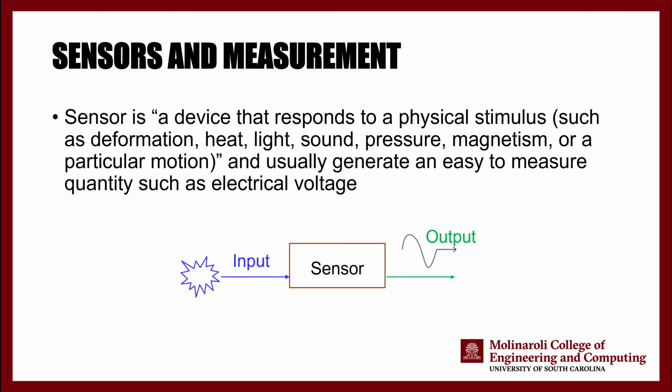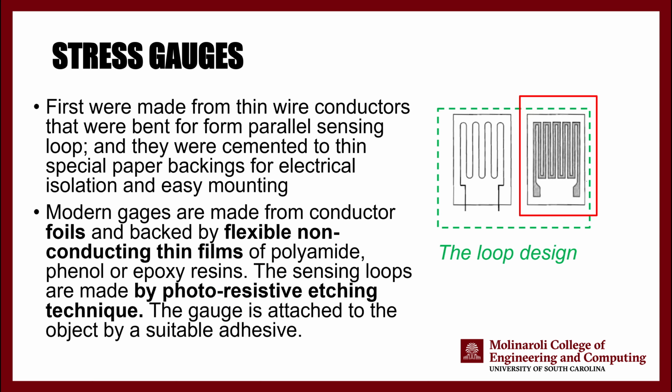So electronic sensors are essentially going to receive an input. In our case, that input is the strain or the stress, which is given to the sensor, and the sensor gives an electric signal. That electric signal is translated in the computer to a stress and/or a strain.